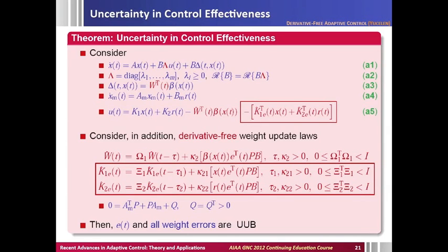Now, up to now, we didn't discuss much the case, even for MRAC, when we have uncertainty in the control effectiveness, because it is common that we have uncertainty. So let's say we have a scalar system, okay? Let's say we have applied our control action to some actuator. Here I am neglecting actuator dynamics. Professor Johnson is going to cover that.